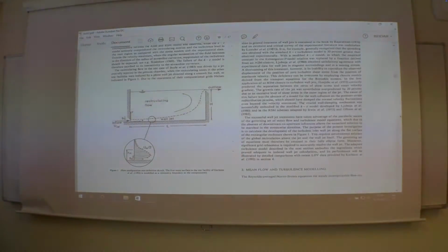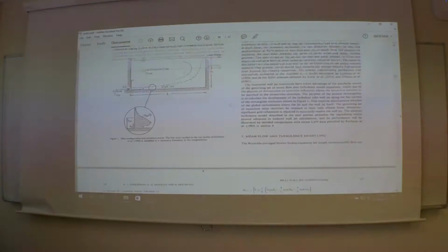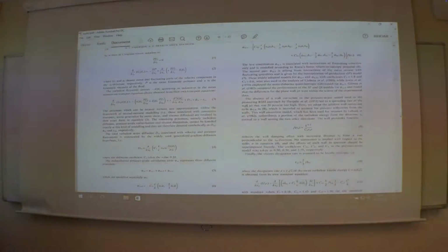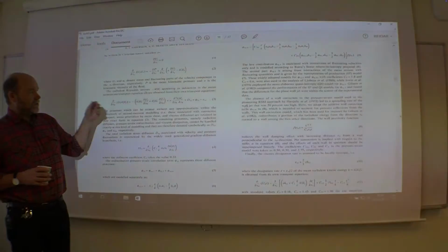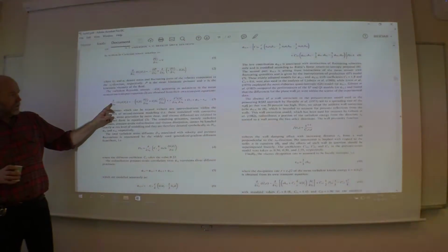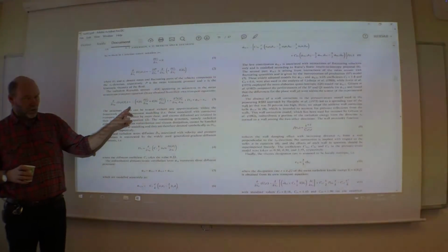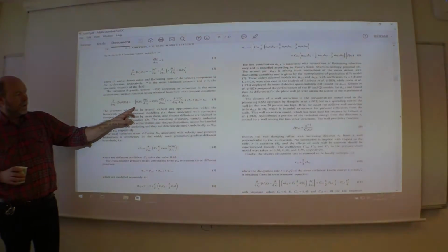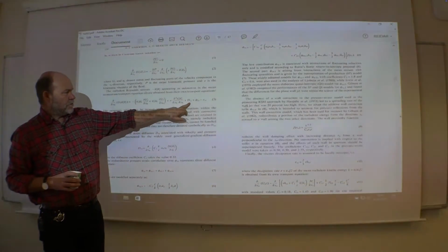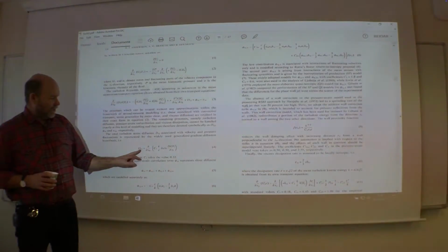And here they play around with K epsilon, and they play around with here a full Reynolds stress model. As you see, quite complex. The production term, no modeling needed. The diffusion terms, he needs modeling.